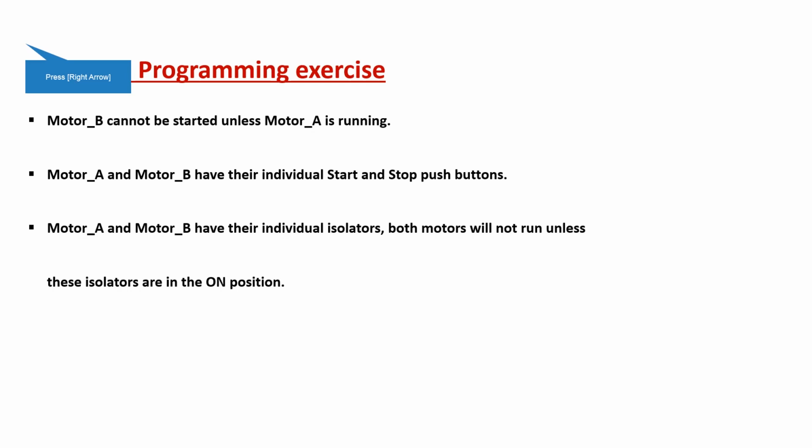It is less than 24 volts, about 5 volts. Are you with me? So the input module takes 24 volts, but the CPU looks at 5 volts. It is actually executing those instructions as 5 volts, which equates to 1 or 0.